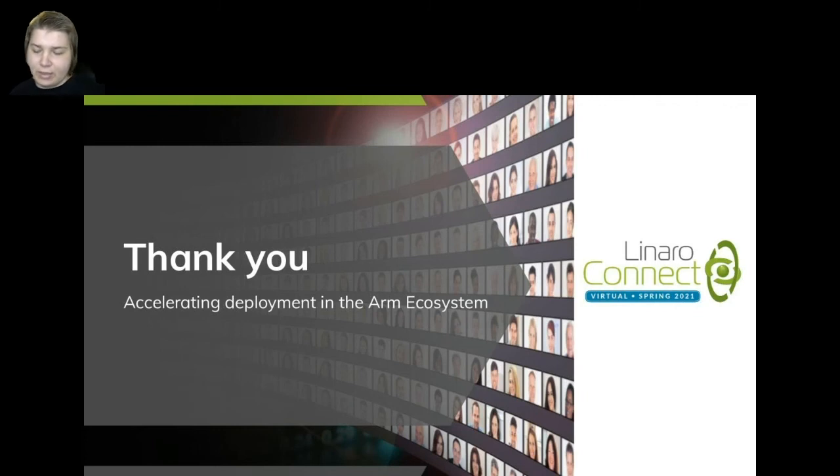Now it's basically that you have your UART mezzanine, and it goes on top of every other mezzanine. And if, for example, you have a mezzanine like the FPGA one, which doesn't have the low speed header anymore, this here is not the low speed header, that's a custom header, then you were basically screwed. So I am planning on building such a mezzanine as well, to just have your UART and pass through all the other signals.